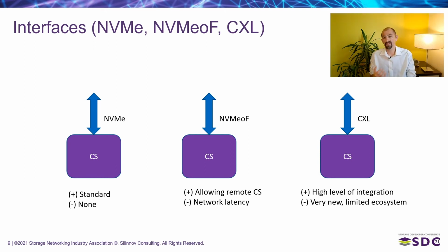On the interface side, computational storage devices are based on the NVMe protocol. That's obvious because the latest high-performance SSDs are coming with the NVMe interface. And it was the easiest way to design computational storage by hiding computing in such SSDs. And for the management of the computational storage commands, we can use the NVMe protocol differently.